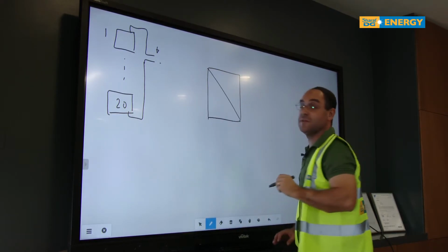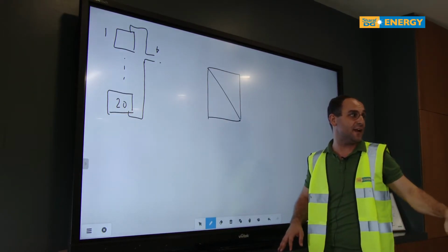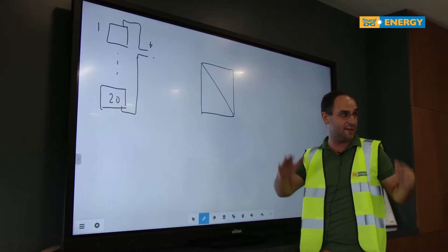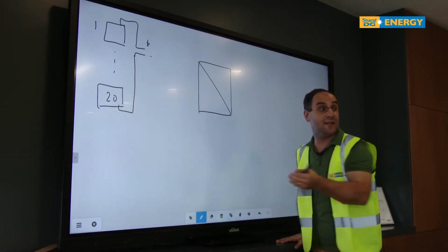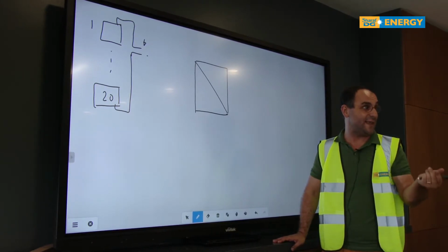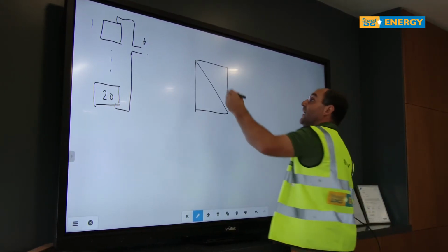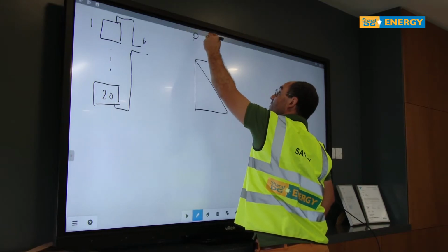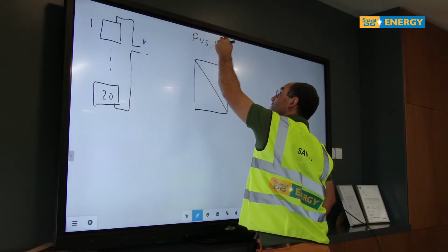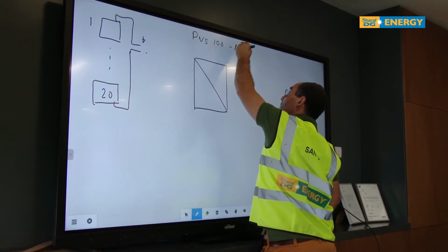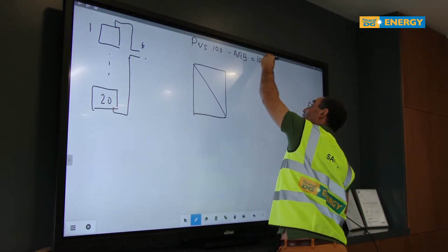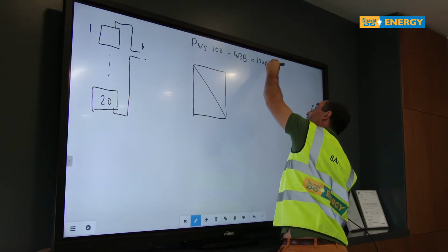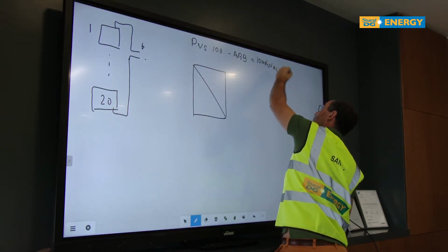The inverters are the machines that you have in the old archive room and in the factory, these big noisy machines, right? These machines are also rated by a technical sheet. The ones that we have on this project are called PVS 100 from ABB, which means that they have a 100 kilowatt AC output.